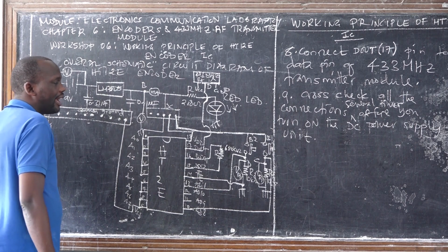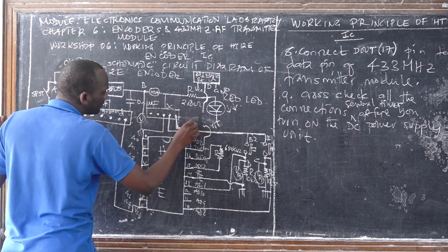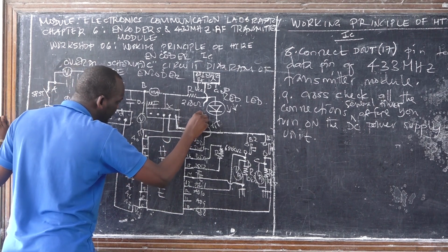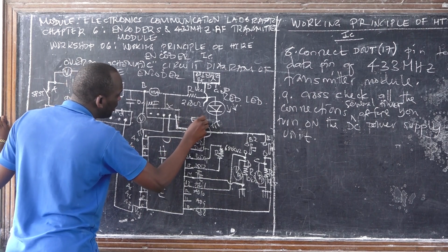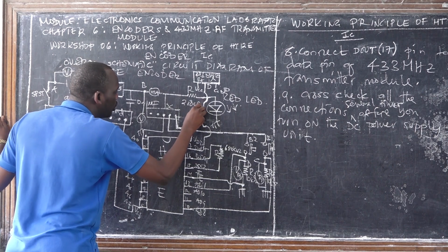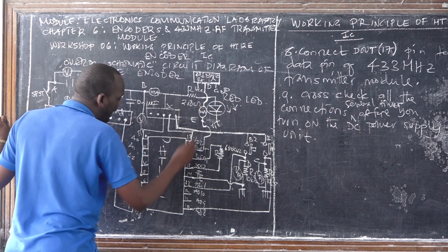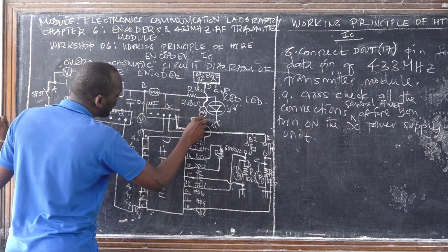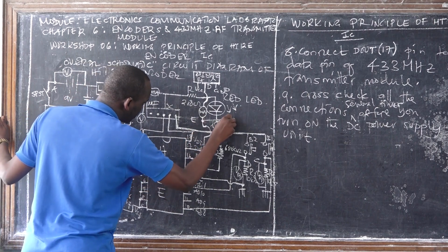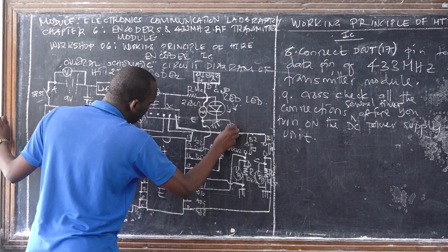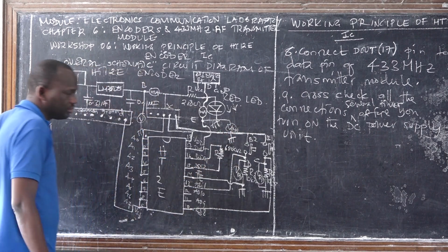Another testing point is this one. So this is another testing point at D out. We have another testing point, we call it testing point E, where we have to measure two parameters. The first one, we have to measure the output current. And the second one, we also have to measure the potential difference. So we should have V out, or a DC voltmeter to measure the V out.